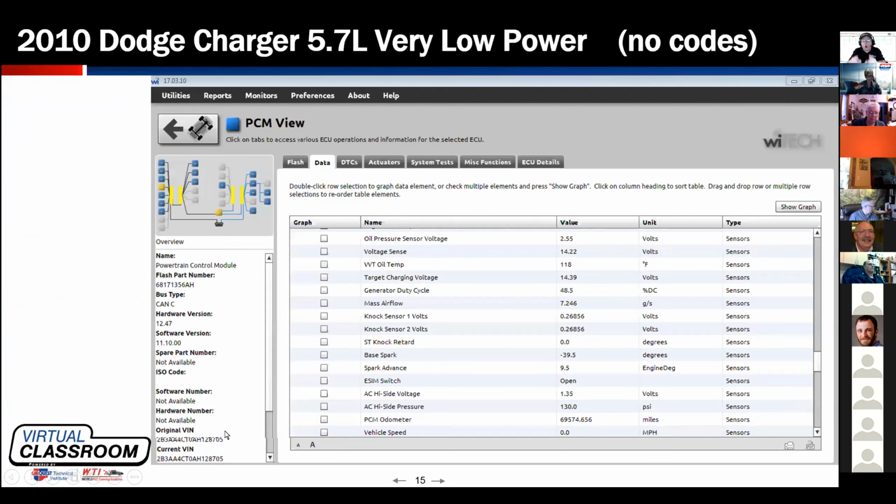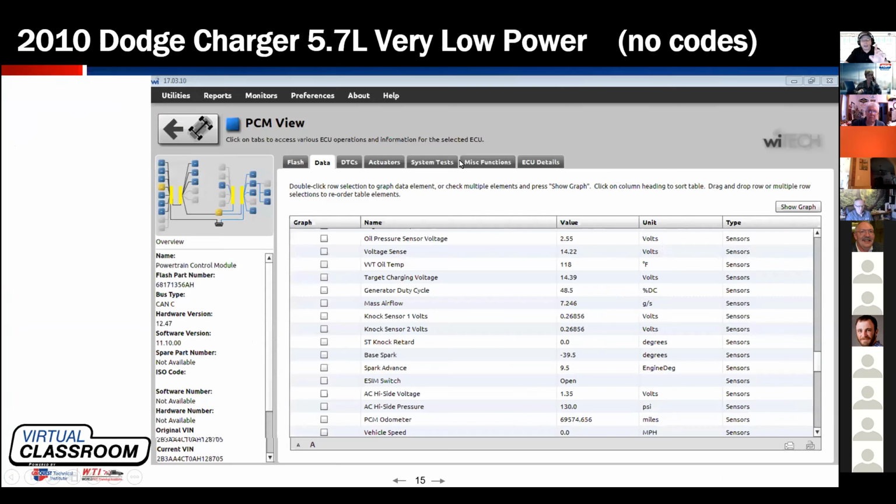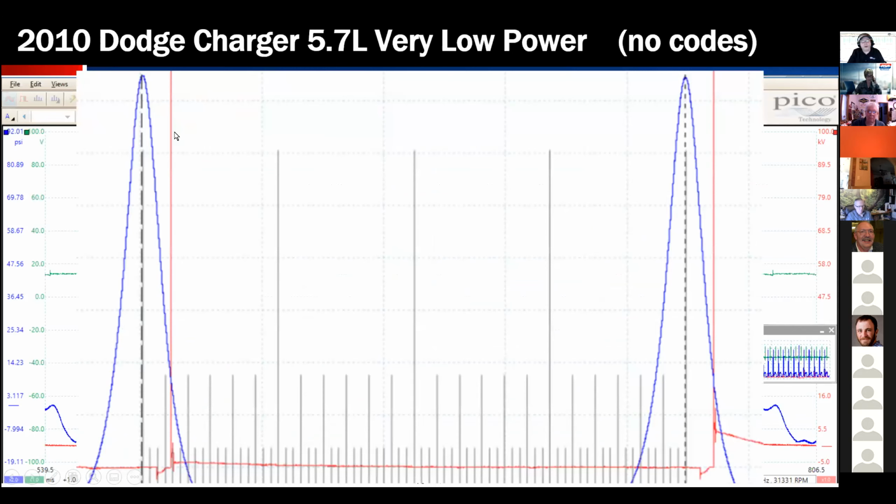Because on your known good car, he said 10 degrees. 9.5 degrees is where he thinks the spark is. By mechanically looking at it and taking the measurement, it is happening before top dead center at a factor of about 11 degrees, which tells me my known good car is not lying. I verified these numbers look great. Yet on my bad car, we saw almost exactly the same massive retarded ignition timing.